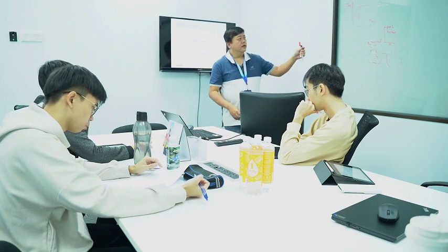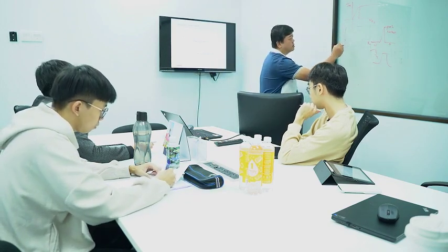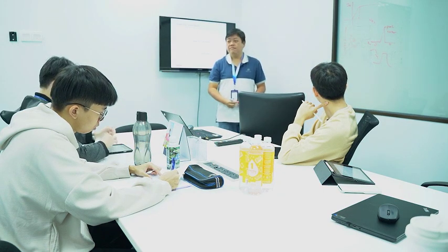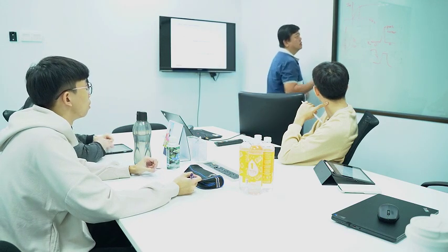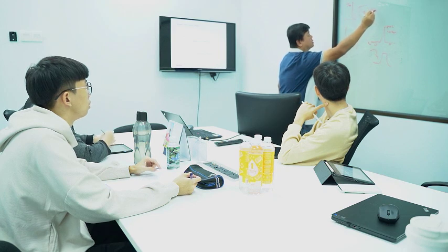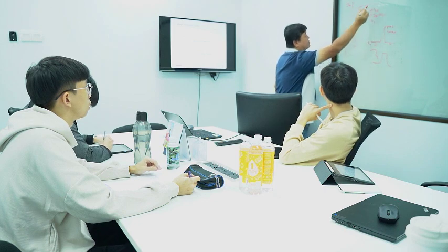So basically, I mentioned to all of you also, a current source has a very high impedance. If you have very high impedance, this is a must have. You look at the curve here. You take R equal to delta VDS versus delta IDS. Where this is pushing 0, actually you have an infinite impedance, right? That's why we call it a current source.